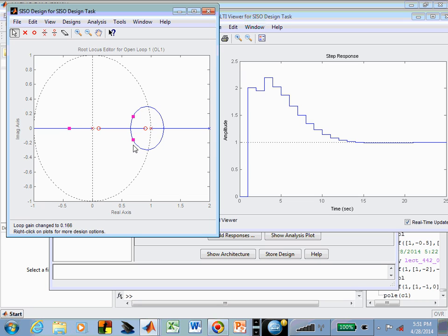So now what we're doing is we didn't introduce any kind of sampling frequency. So this time is maybe misleading. This time is really just the number of samples, meaning we are going in maybe a 2 sample period delay, and then we kick up to 2, etc. So we don't know what our sample period is. It was unspecified, but that's just the number. So by the time we get out to about 14 sample periods, we've settled to our final value.